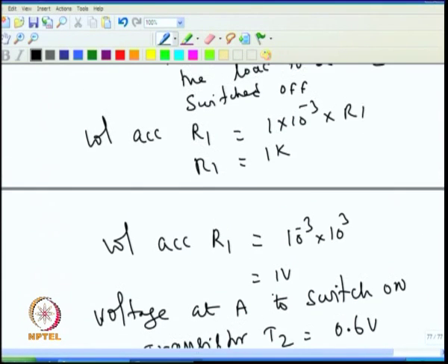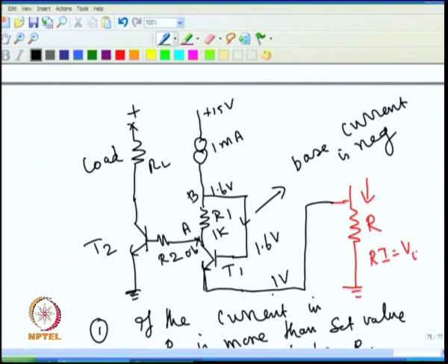So, the transistor acts like a comparator. So, we got switching, that is, when the voltage at this point goes more than 1 volt, this transistor will be on. When the voltage at this point goes less than 1 volt, the transistor will be off. And by doing this, we have done this particularly for one important advantage, that is this switching voltage. We say now 1 volt is our switching voltage. This 1 volt is independent of the temperature. For example, if I have not done this arrangement, when temperature changes, then the required voltage to switch will change.